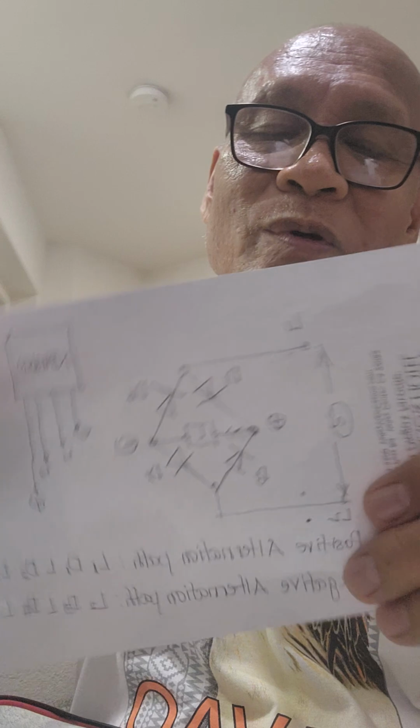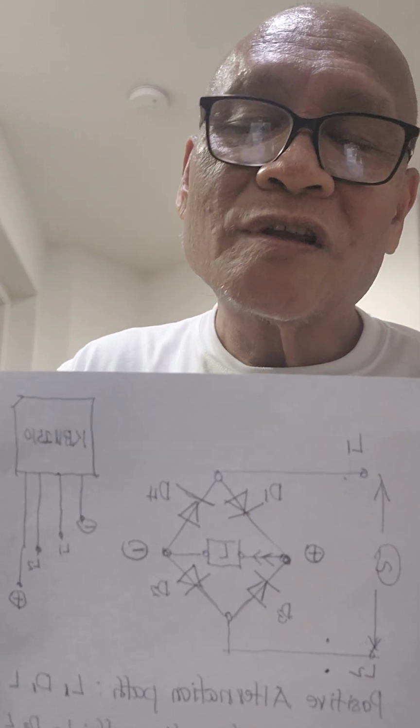Try to memorize the figure first, guys, then I will bring it down. I could demonstrate how we check the four individual diodes. For a diode to be checked using the tester here, we place it on the diode. We change the mode. There's a diode mode already here. So there will be two terminals.